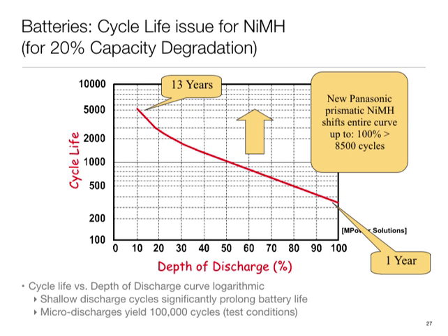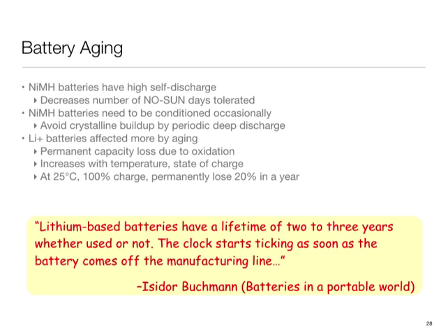So on the micro discharge recharge, I believe there was a time where they recommended you always discharge the battery down to 20% and then charge it all the way back up. Is that still true? So that's not true, and the only reason for doing that tended to be to calibrate the battery. For the sensors, by which I mean software plus hardware, which give you the estimate of the battery life and all, the only way for it to know this is to go through that complete cycle. But a total deep discharge, where you leave it like that, damages the battery.